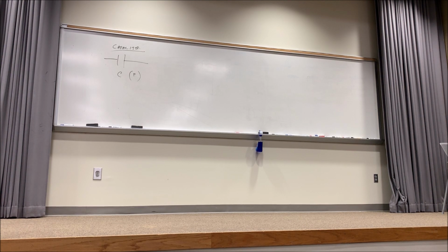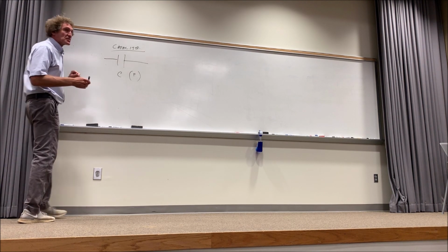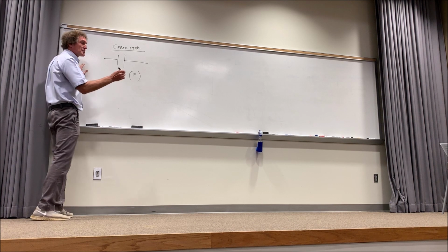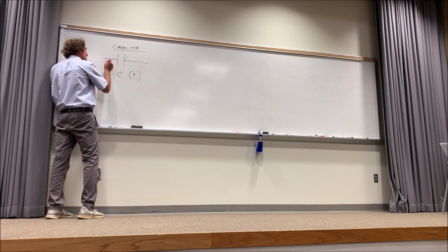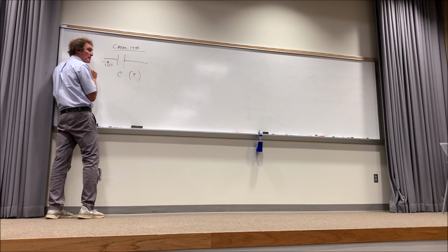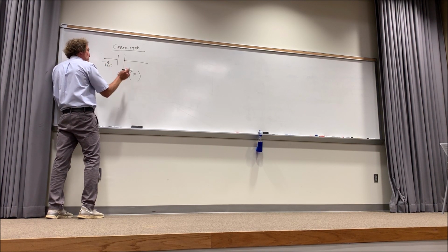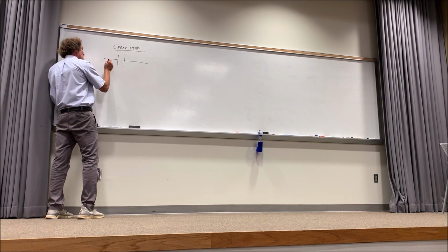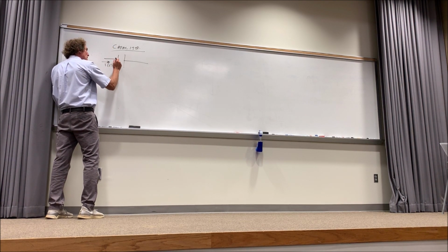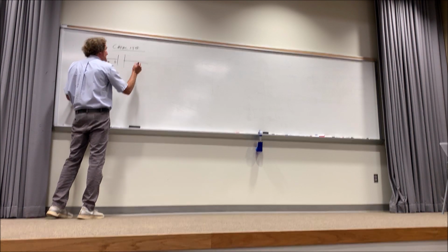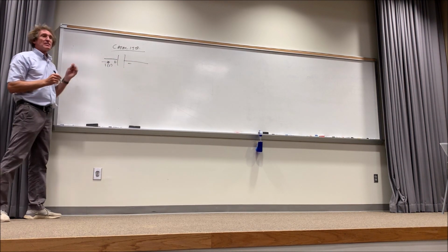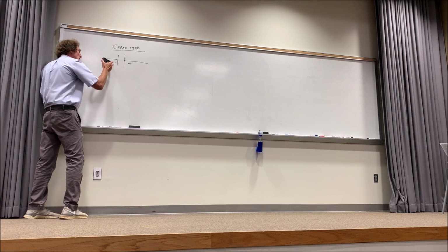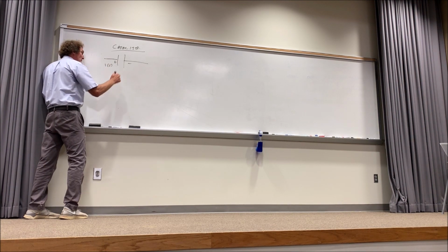That's a capacitor. The thing that governs capacitors' voltage-current relationship is this. Please write this down. If you have a current i(t) entering a terminal, you will label the terminal that the actual current is entering as plus, the terminal the current is leaving as negative. Now again, I'm defining that as the direction of current means that I'm assuming it's going that way.